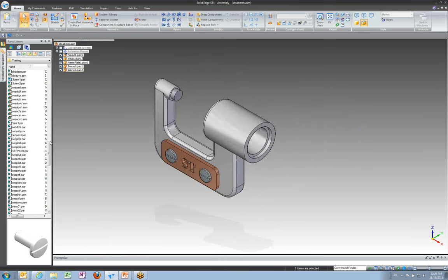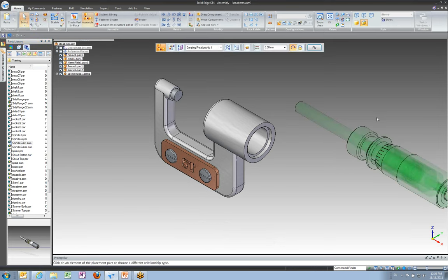The last thing we're going to add is the whole spindle assembly. This is the part you actually twist to move the micrometer. And instead of this being a part, it's actually a sub-assembly. So it's already an assembled collection of parts, but we're adding it in as a sub-assembly. So I'm going to find, I think it's called spindle sub. There it is, spindle sub 1. I can see in my preview that that's what I want. So I'm going to click and drag, and I'll bring my mouse over here and drop that into space.